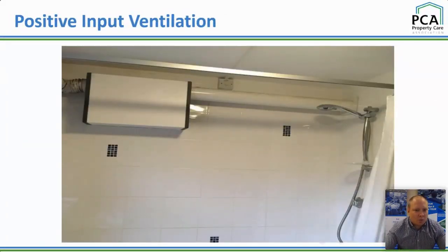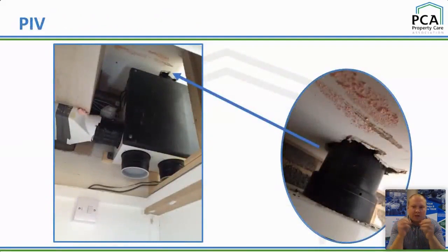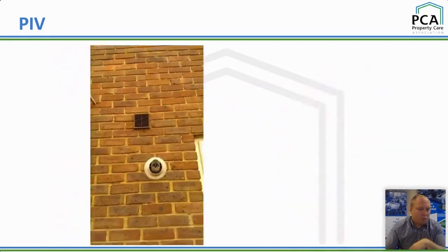Unfortunately, you wouldn't want that in your shower, would you? It goes to show another one, because what you're doing is pushing air into the built environment, or into the occupied space. In this scenario, obviously, you've not got a sealed loft area, so it will be forcing moisture-laden air up there and recirculating, causing a problem.